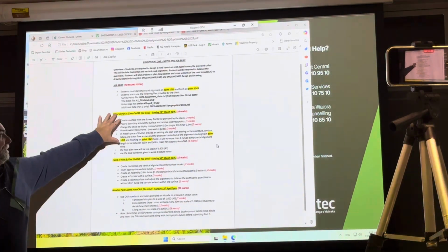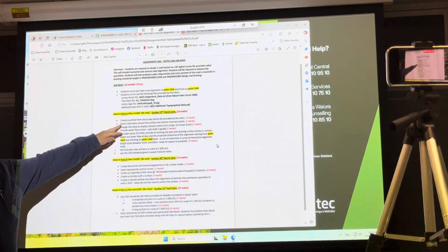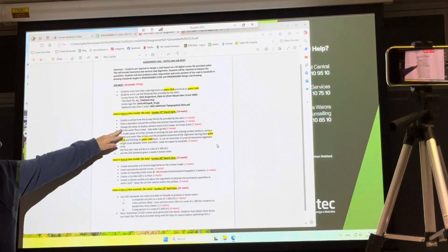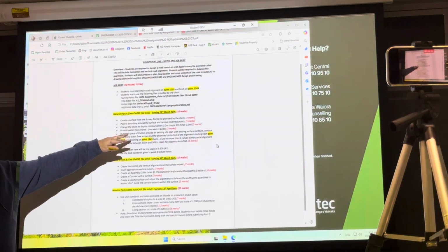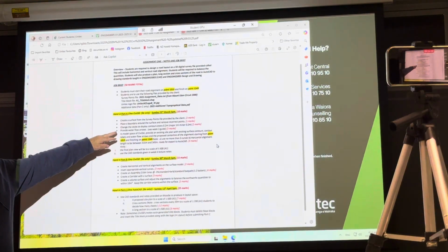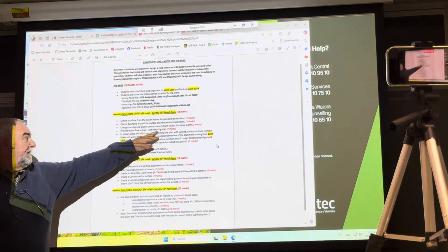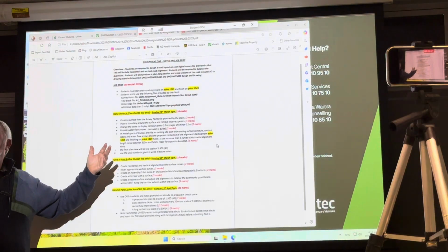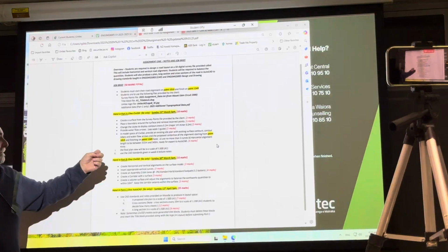So we start off with part A. Creating a surface, we did week 1. Placing a boundary, we did week 1. Changing the styles to display the contours every 0.2 meters, major 1 meter, minor 0.2 meters, we did week 1. Water flow arrows, it says see week 3 guide, so we're bouncing around a little bit. None of that was tricky, it was all explained. You probably won't have to do too much extra work.